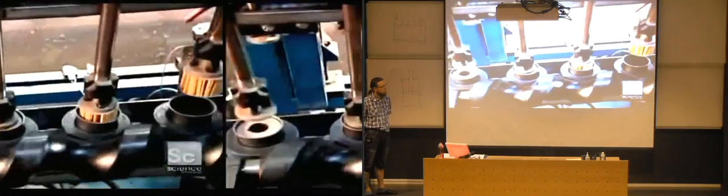Now for the final assembly. As the canisters go by upside down, automated arms insert the filter cartridges. A worker then puts a thin rubber disc on top of each cartridge. This disc will prevent the oil from draining out of the filter. Now for those bottom assemblies we saw them making earlier. A worker positions one on each canister.